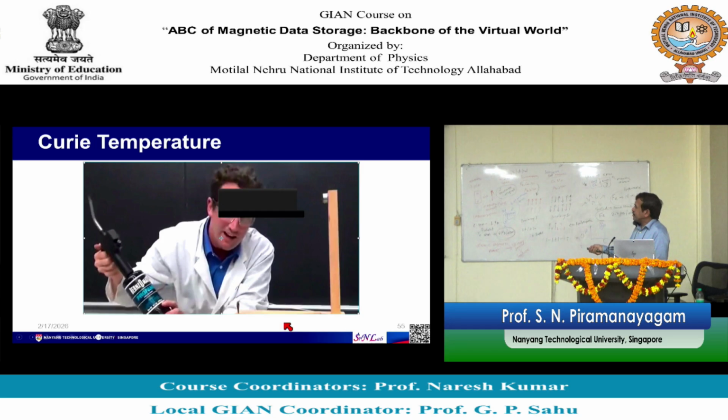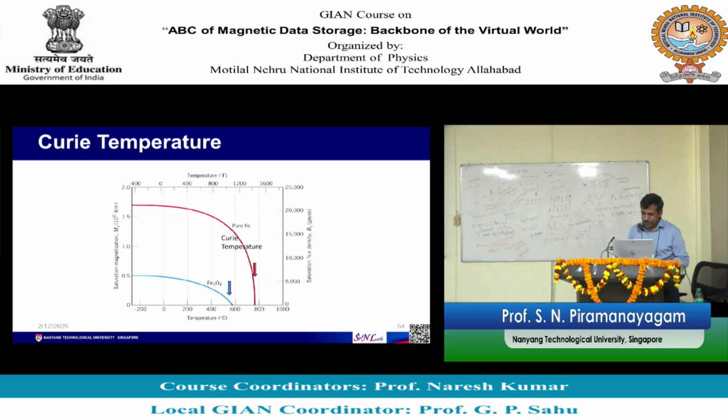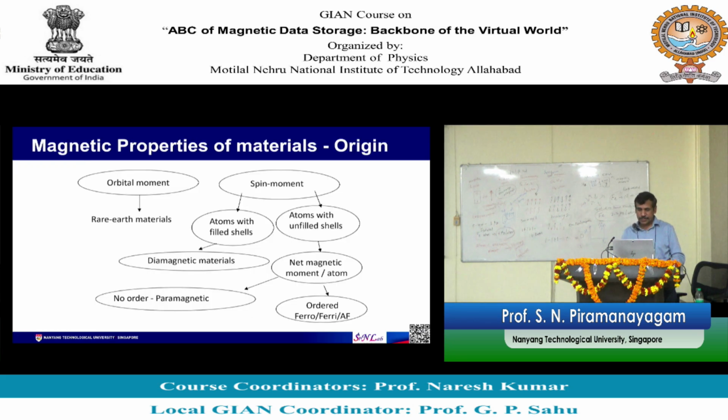Okay. So, now the clip is lying down, it got cooled to room temperature. So, will the clip become ferromagnetic again? Yes. Okay. So, if you look at this picture, above this temperature it will become paramagnetic, but if you cool again it will become ferromagnetic. So, this curve is more or less reversible. Some materials may have some hysteresis loop here, but mostly it will go back along this path. Okay. So, materials will gain the ferromagnetic property again once you cool down below Curie temperature.